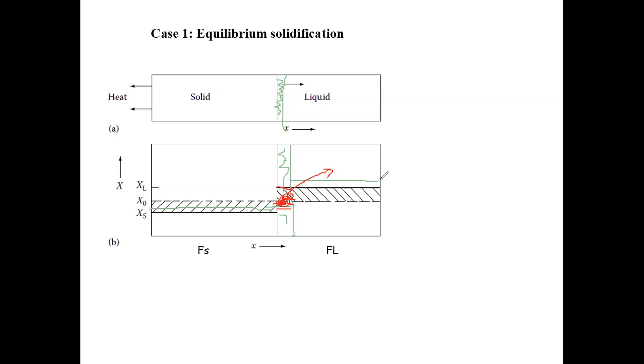So throughout the liquid, now we have the new equilibrium composition, and this is when equilibrium is achieved. So this is the process by which you can maintain equilibrium, yet slowly drive the growth of the solidification front. Okay, so that's basically this process.